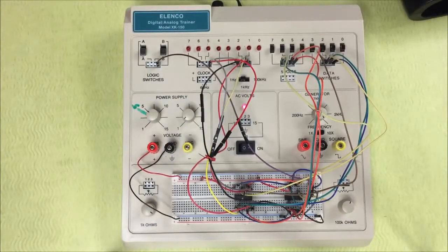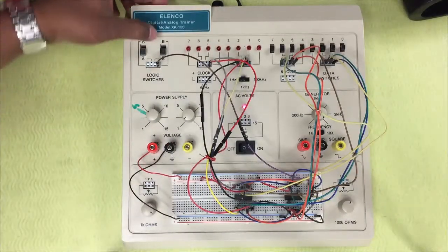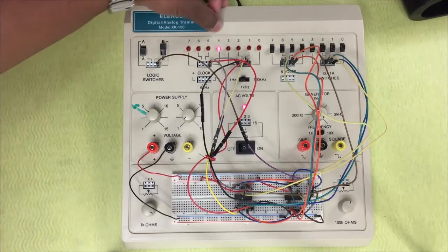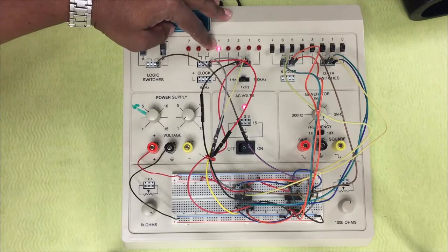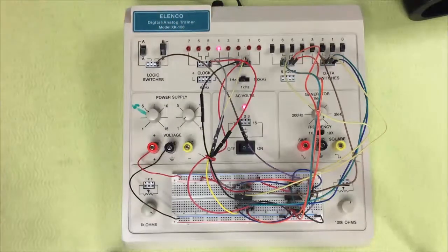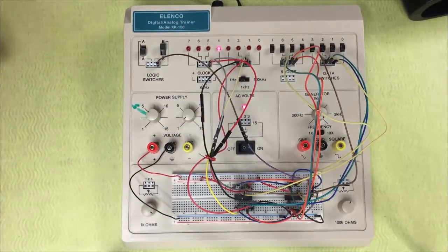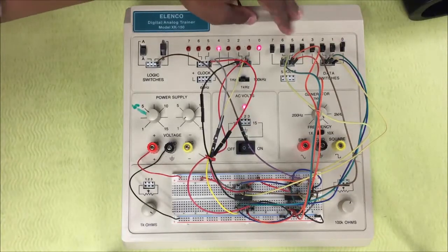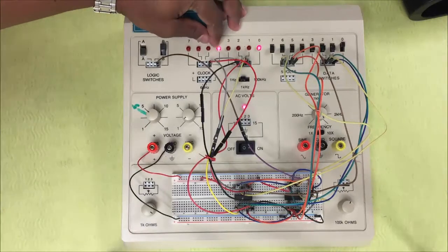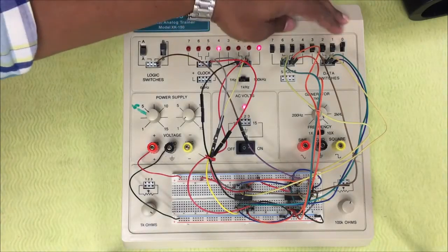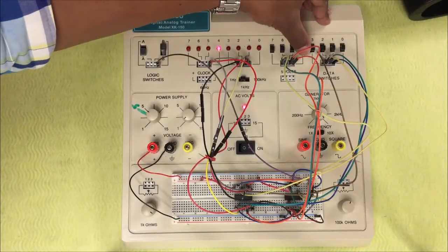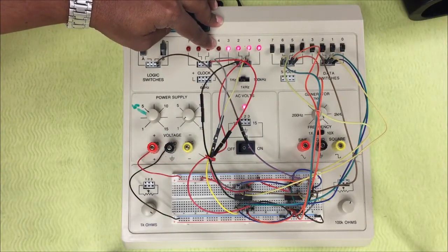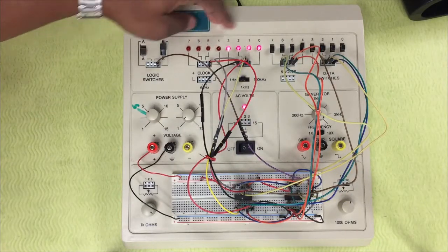For the adder/subtractor, we use an additional input to select between addition and subtraction. For subtraction, B equals 1. The carry indicates the sign. If we calculate 1 minus 0, the output will be plus 1. If we calculate 0 minus 1, the output will be minus 1. Here the output is shown in 2's complement form. Similarly, we can check different input combinations and verify the output.